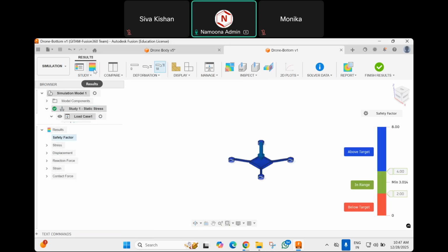In the results tab, go to the results menu. And now we are interested in finding out the stress. Click on the stress, and inside the stress, we want to see the von Mises stress.